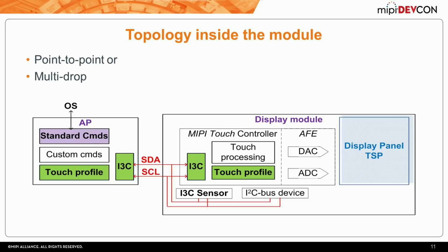One of the key items of what we're working for is we want to shift to I3C. I3C provides us a couple very nice features. One is it gives us higher bandwidth, and we can dynamically move between the bandwidths as appropriate for the design you're on. Secondly, I can actually include additional devices, even traditional devices. So it lets things like, maybe I have multiple touchscreens because I have one in the front and the back and I want to handle them differently. Maybe I have just general sensors. I have some traditional, I have an I2C PROM or something else I need. All of those can be easily integrated, where in the current situation, it's not an easy thing to put together.